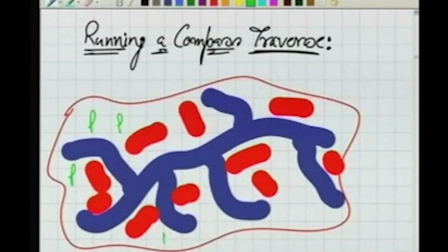As usual, a ground may be like this, and we want to make a map of this ground with the compass traverse. We want to plot the entire boundary of this township, all the roads, all the buildings and all the trees. What should the steps be? Where should we begin? What should we do? So the very first step in order to make a map will be, as usual, the reconnaissance survey.